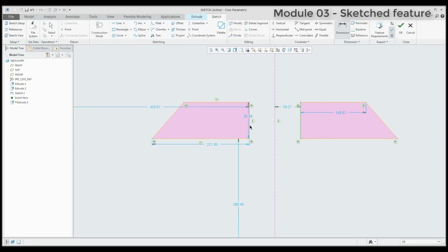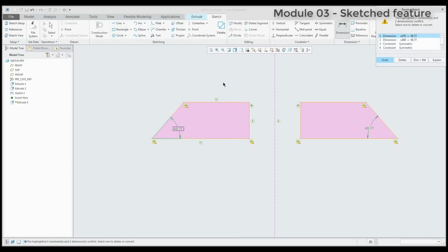You can select the references and you will see the dimensions, or you can continue and confirm with the middle button. So select one reference, confirm with the middle button, and set the dimension, for example 150, or select more than 2 references and confirm again. What's happened right now? On the left side and right side I specified the same dimensions.